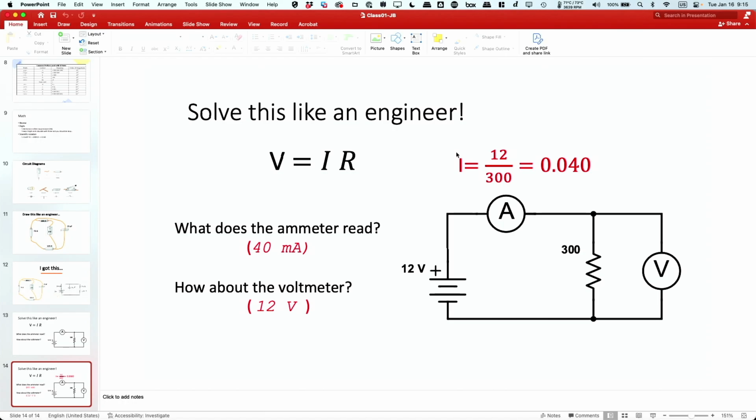So in order to get a positive current, an electron would need to leave the bottom of the battery and go up through the resistor and into the positive side. That gets confusing, so we're just going to imagine that there's some mythical positive carrier here. Our little charge-carrying canoe, carrying 1 unit of positive charge, comes out of here and goes down this wire. It has a choice to go to the voltmeter, but that's very high impedance, so it probably is not going to make that choice. It's going to go down here, and then where's it going to go?